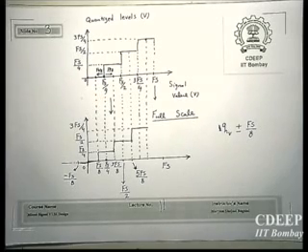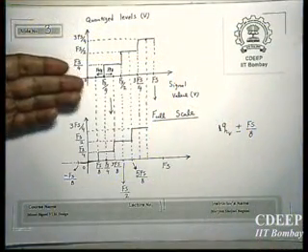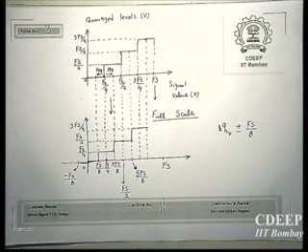You don't give enough margin for negative noise, instead you are increasing the positive noise margin. So it's better to have equal positive and negative noise margin. That's why even for positive signals, the second one is preferred.